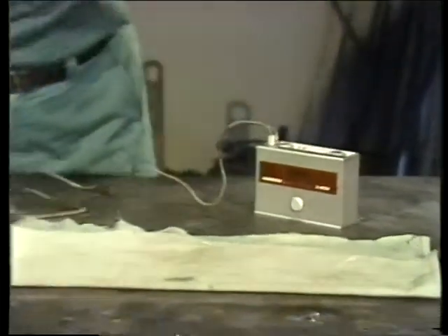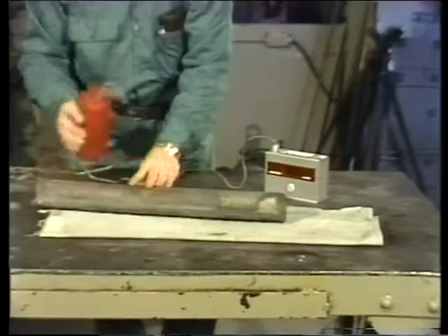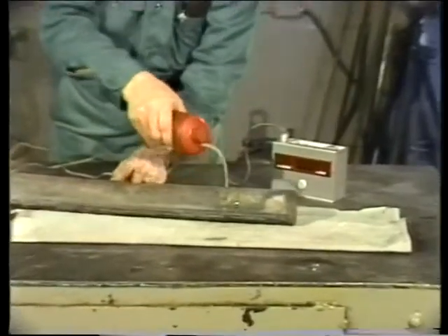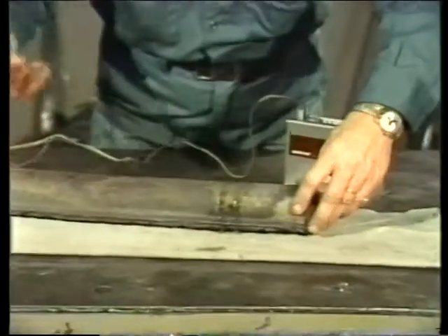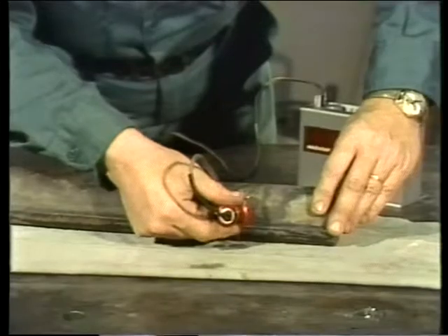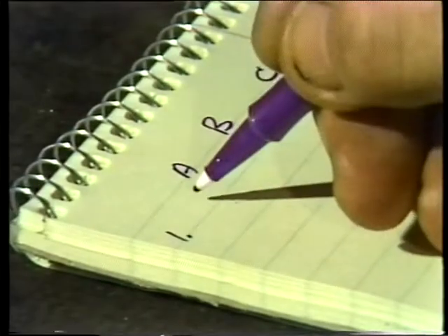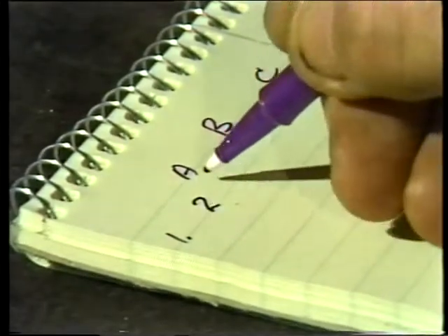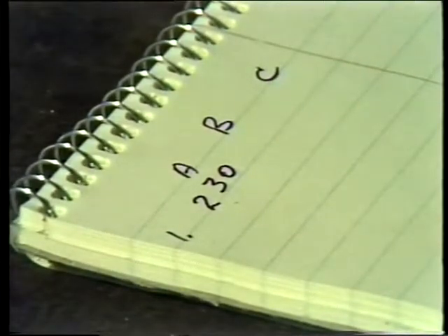Now, to check a tube wall for erosion, spread couplant over the tube. Now, this tube has been cleaned. In a boiler, you'd probably have sandblasted it clean first. At specified intervals, take measurements around the diameter of the tube. Record each measurement carefully so they can be compared with the known thickness of a new tube wall. If the walls are too thin, the tubes must be replaced.